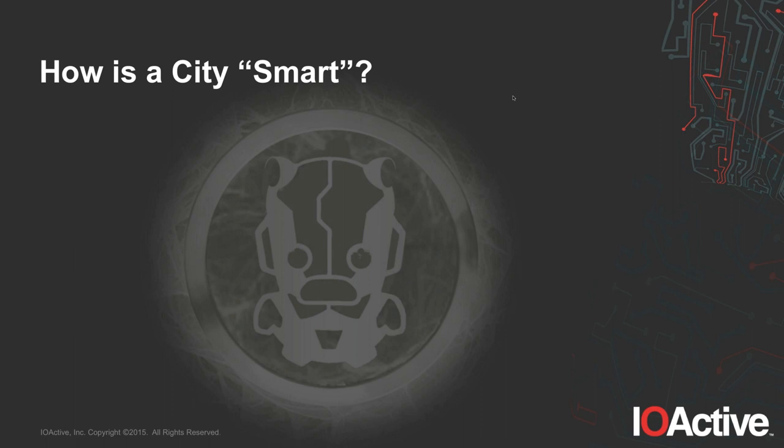So how does a city become smart? What technology is being deployed and how is it being used? So we have smart technology for traffic control. This technology basically helps to detect in real time the traffic on a highway, in a street, at an intersection. It will use this information to adapt the traffic signals, the ramp meters, etc. So instead of having fixed timing on the traffic lights or ramp meters, it will adapt based on real-time information provided by sensors, by radars, by cameras, etc.